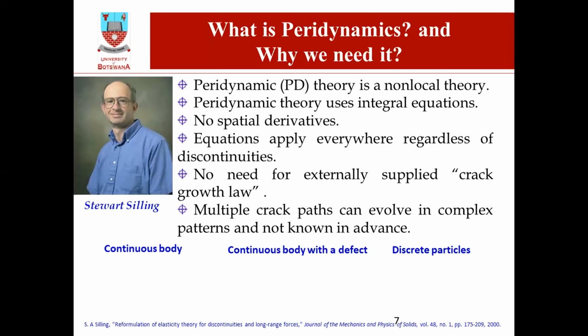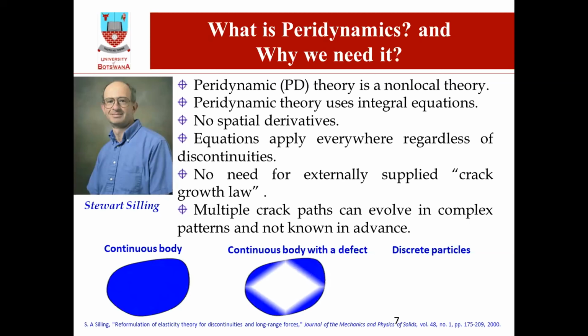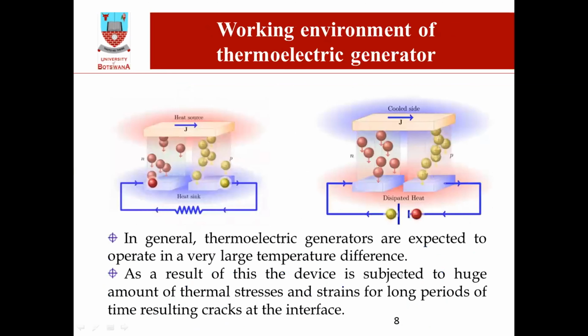The other interesting feature of peridynamic theory is it can capture multiple cracks and discontinuities. If you have a continuous system and there is any discontinuity, as I said before, this non-local theory captures it, interestingly, using this mesh-free method. We call them material points.